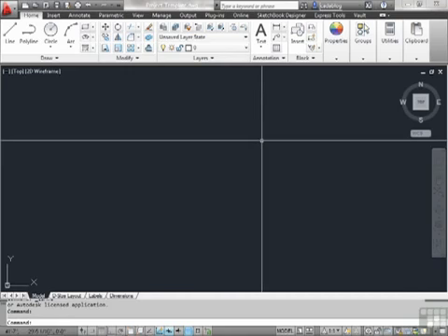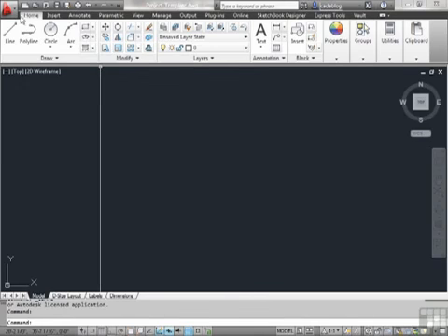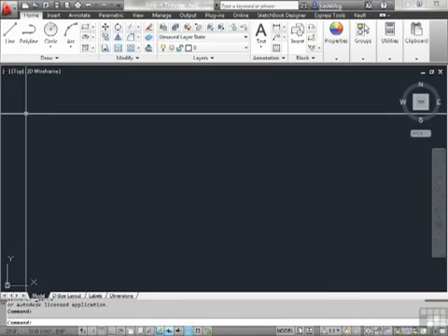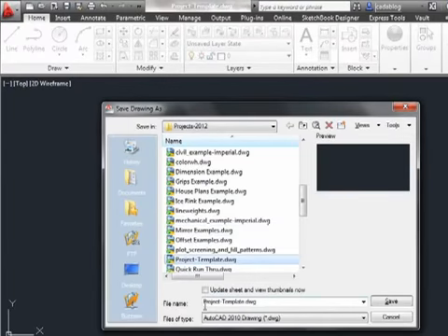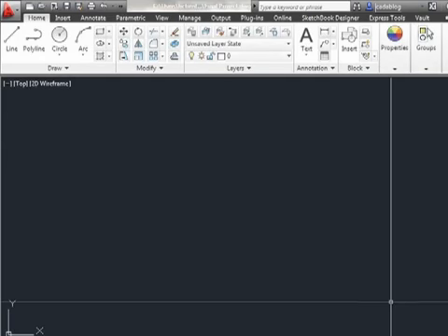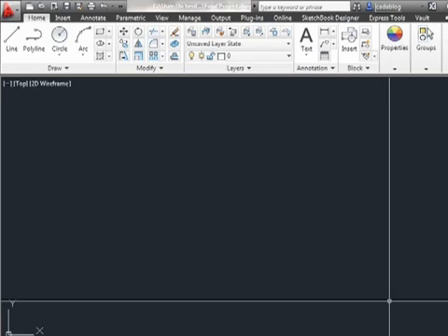First things first, good CAD practice means that once you open up your template file, you automatically go with a Save As and call it your final project. Click Save. Now you won't make any changes to your template file if it's a DWG or a DWT file. You have a file that's unique to this project.